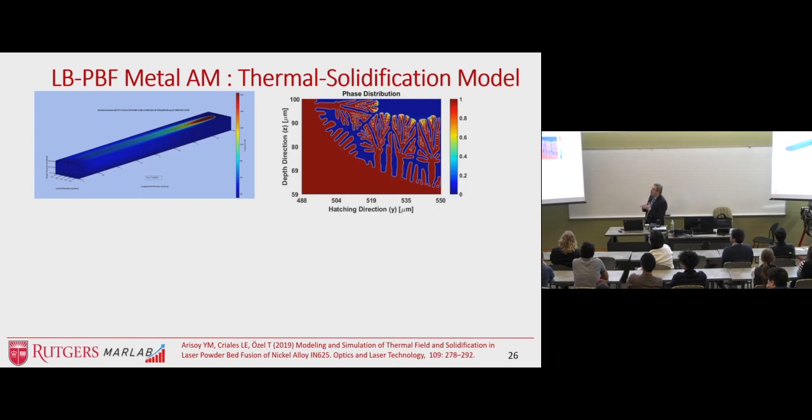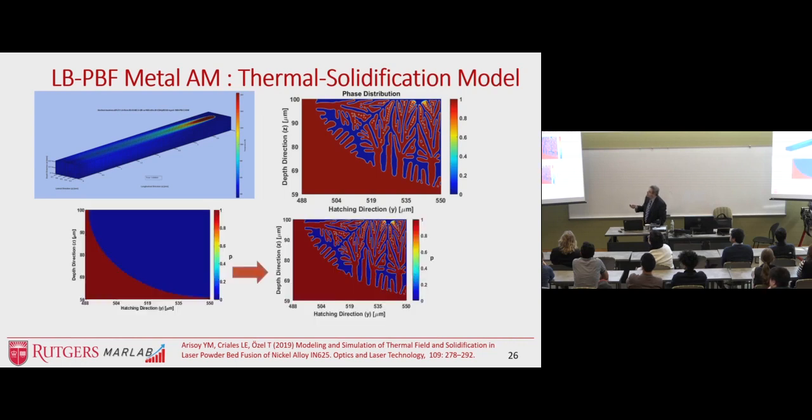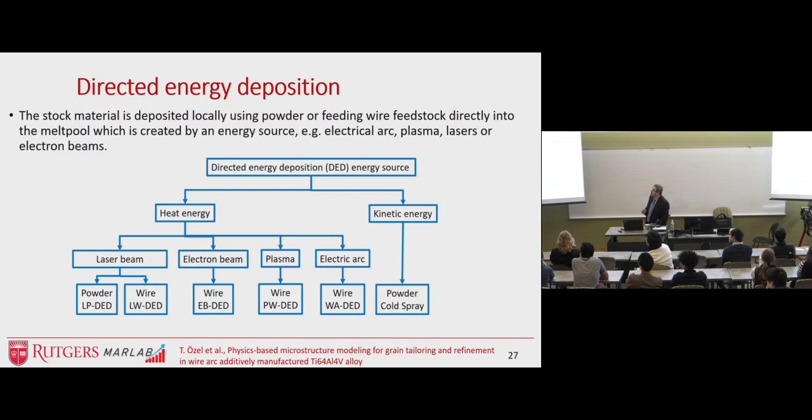Now, this tells us the time the solidification takes, what the growth directions are, and whether the process can be controlled by changing its parameters. So this is a digital model that needs to actually be intertwined with the physical system. Here's the melt pool boundary and the solidification dendrites moving into the melt pool in the simulation results.